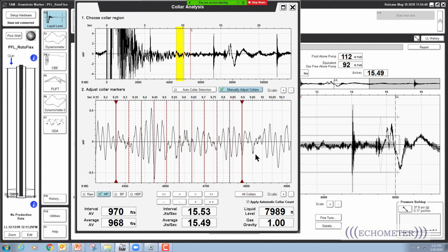Sean, that's an interesting question. Normally we don't really think about the gases moving. We just assume that the in situ gas has a certain pressure and temperature and has an acoustic velocity. I don't think I've ever done any kind of study to see if the acoustic velocity going with the gas is faster than the acoustic velocity coming back up. But it should, I guess, give you the same overall acoustic velocity, correct? I think it's got to be the average round trip travel time, but I don't think it would really matter.